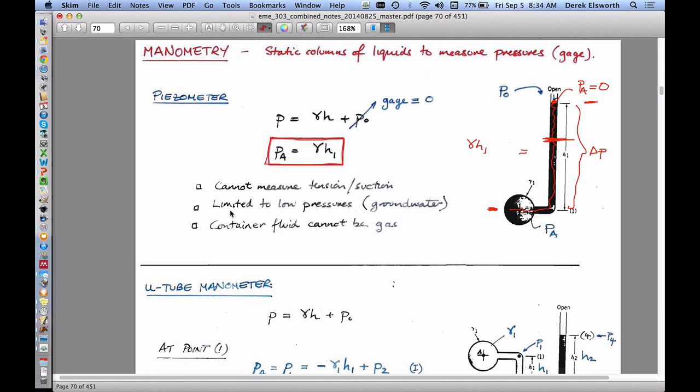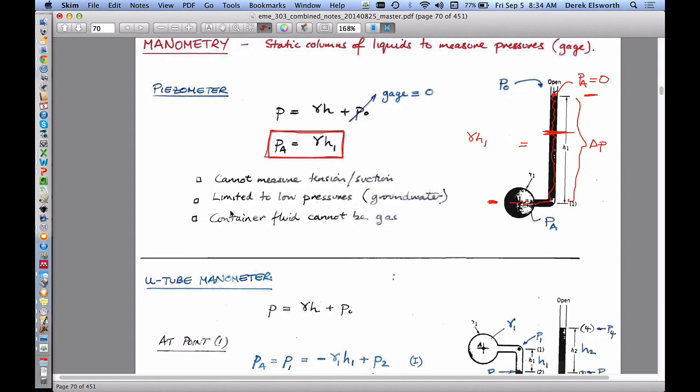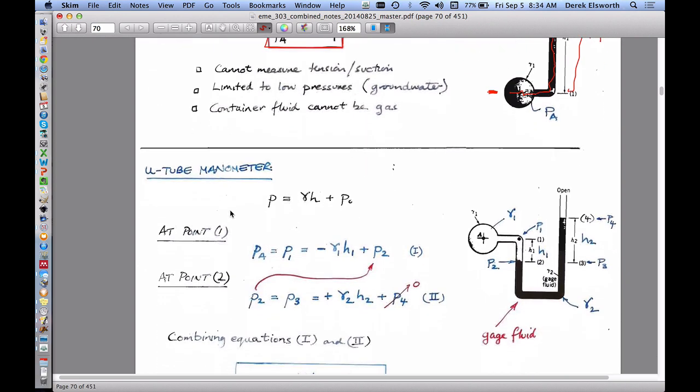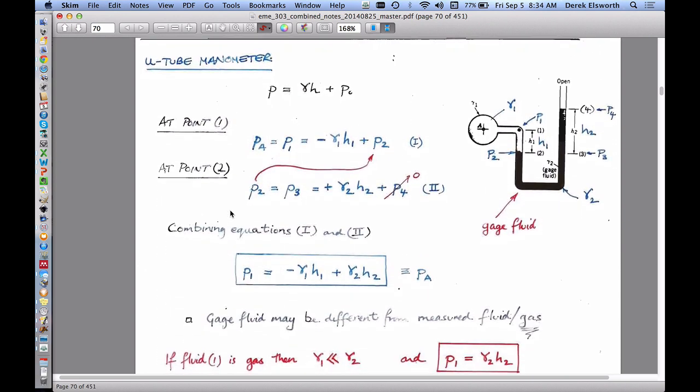And so, with a couple of caveats there. So those are the simplest, that's the simplest kind of manometer. Standpipe piezometer is the simplest manometer. It gets a bit more complicated if we start with systems which are a little bit different from that. And so manometers are cases where, for instance, you might want to measure pressures which are subhydrostatic. And they typically involve a vessel. And so this is a vessel, or you could think of this as a pipeline coming out of the page at you, which is tapped by a tube.